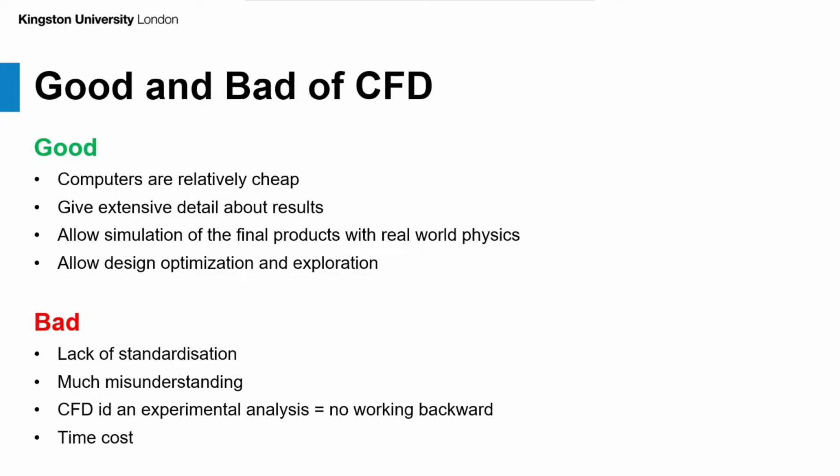And again, it's time. Depending on the mesh quality you have, it might take a few minutes, a few hours, or a few months. In today's example, you can see these are really simple models where we go with the general mesh size, so it's around a few minutes. But if you want to run CFD properly on an Airbus wing, it might take a few months, depending on how much computer power you have. That's why in CFD they use clusters of powerful computers to reduce that time. And that's the other aspect of the cons of using CFD.